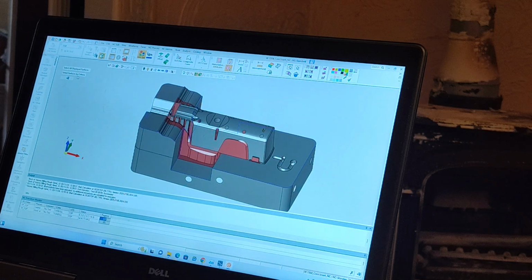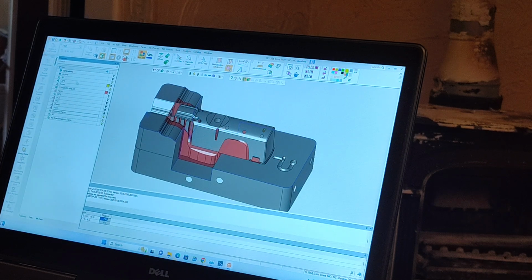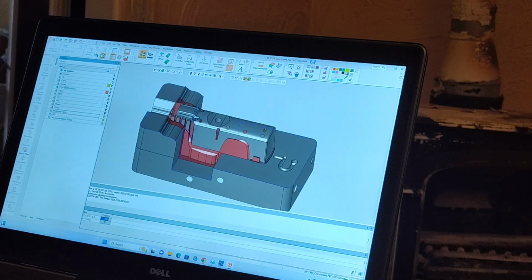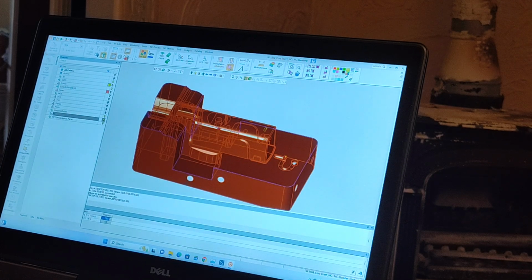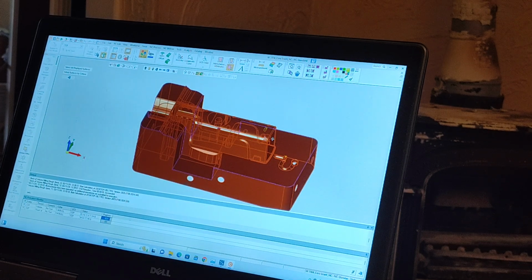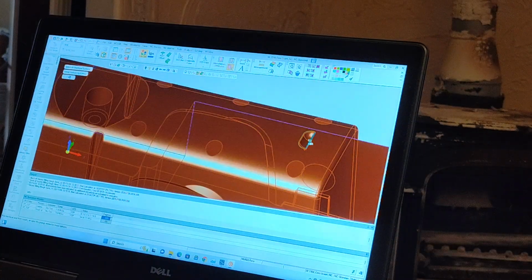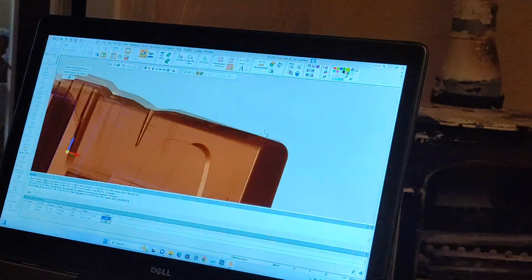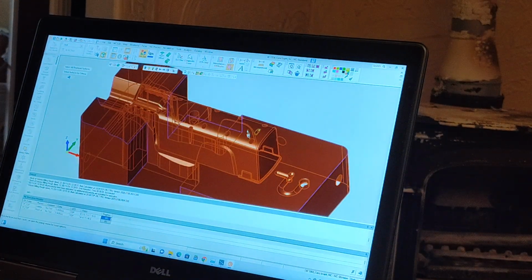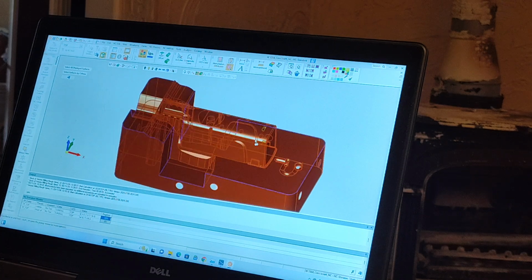If you pull up the sets while we're in the geometry selection area, you can still pick the surface, right click and say select entities. And then by doing that, you can individually turn things on and off, or I guess select and deselect. So that's a good way to select using sets without being hard coded to be whatever's on that set.